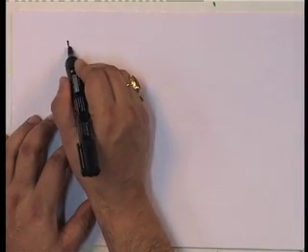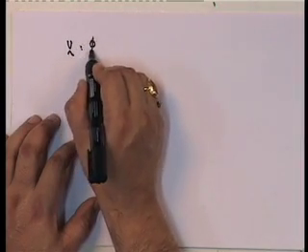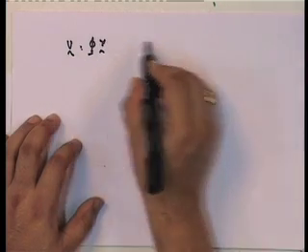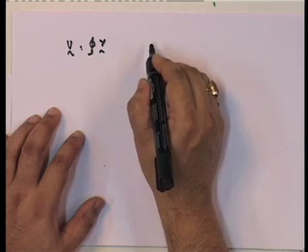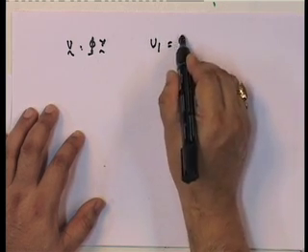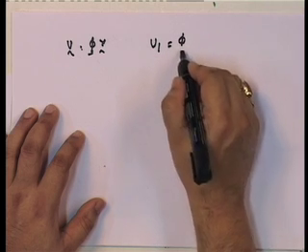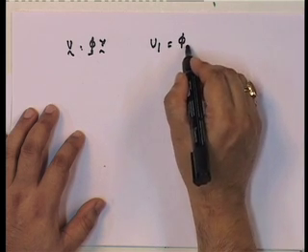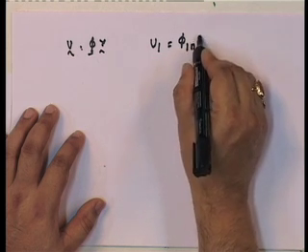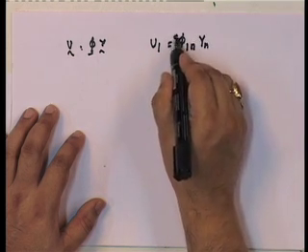So, once I have got y 1 of t, y n of t, I can find out v by doing phi transpose y. Okay. So, now I can also say that v 1 of t is equal to the summation of phi 1n y n.